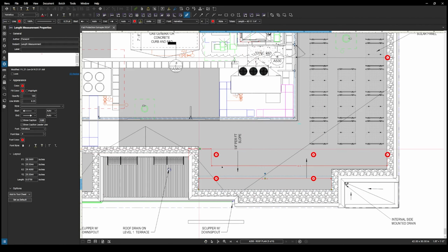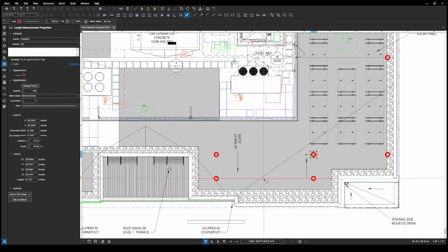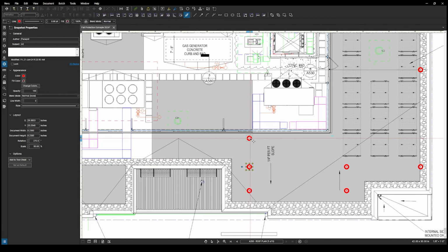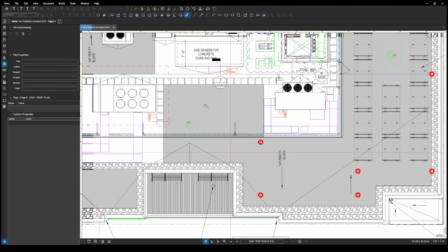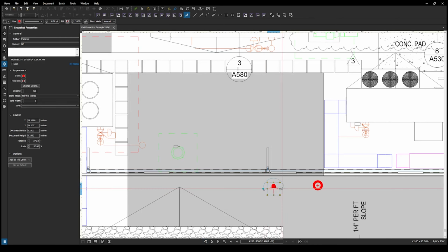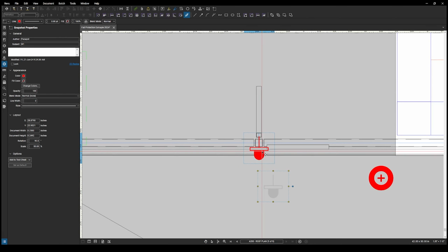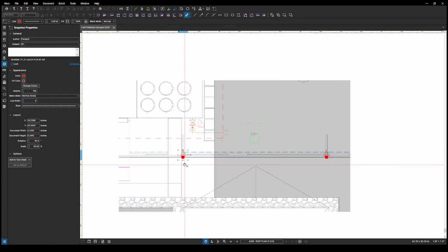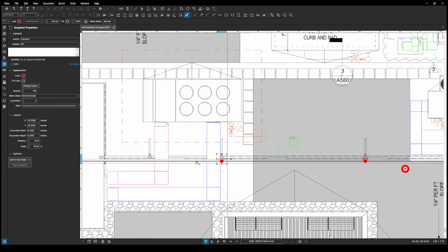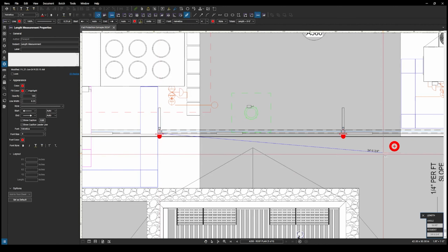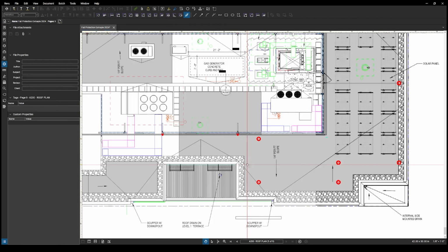However, this drawing here does look like it has, in blue here, these look like they're duct units or maybe some kind of other HVAC type things. And because we're not too sure what's going on there, those things happen with drawings. We have things like the elevations and sections that aren't super accurate because these drawings are early stages. So you plan around that, and to be safe, we're going to stop our cable system on this anchor right here.